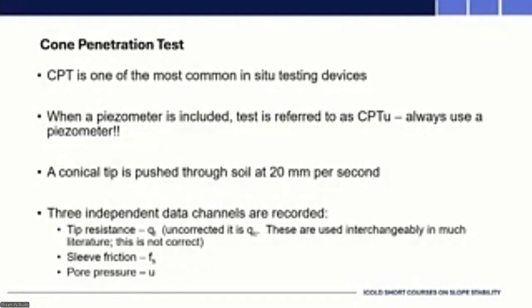And I think, and I haven't looked at this in any detail, people that are more familiar with CPT testing might confirm this, that rate of 20 millimeters a second probably gives you drained behavior in a sand and undrained behavior in a clay. The trouble is tailings don't fit that kind of categorization that easily or that often. And we'll come to that.